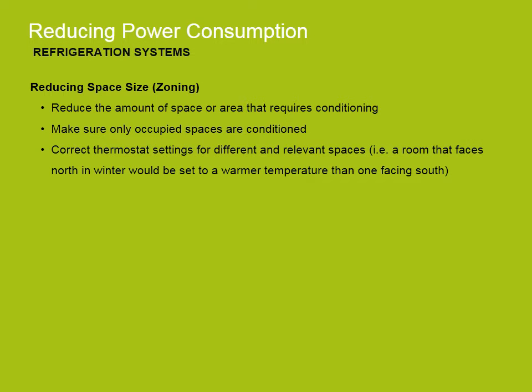Reducing the amount of space or area that requires conditioning will reduce the amount of air conditioning required. It is essential that only the occupied spaces are conditioned. Many ducted systems allow clients to set the correct thermostat settings for the different zones or spaces and for the relevant weather seasons.